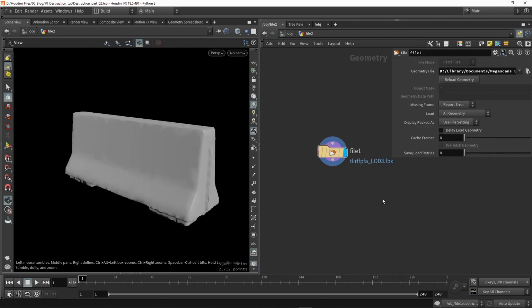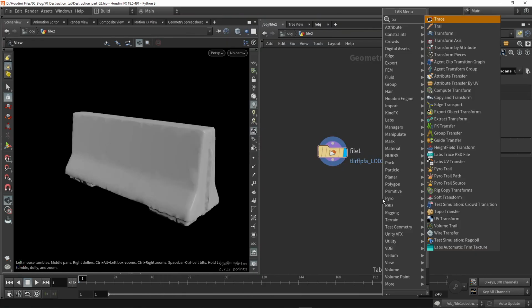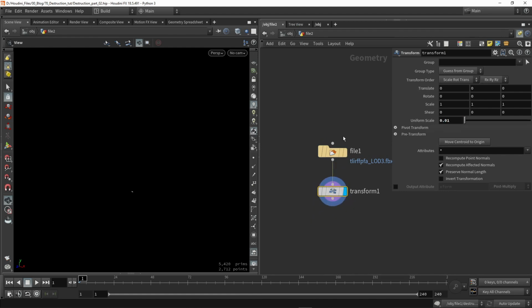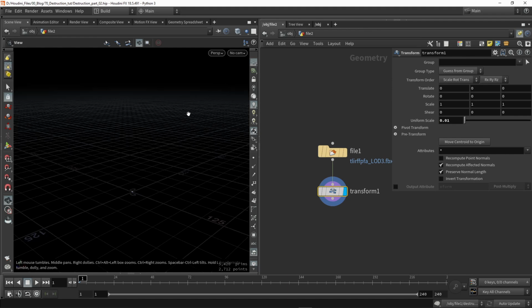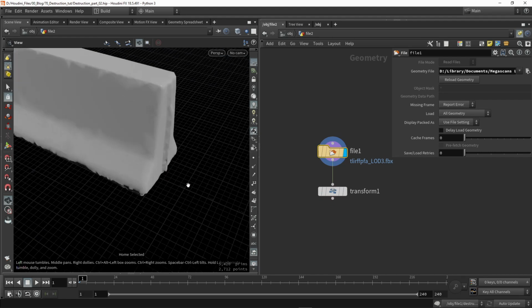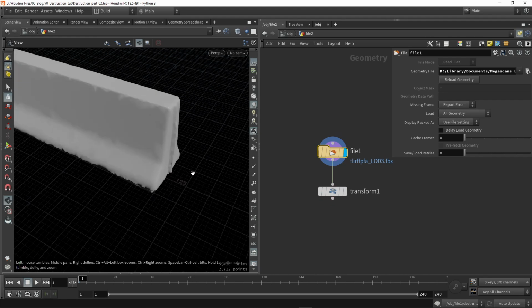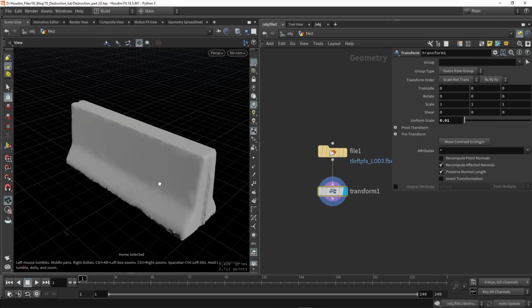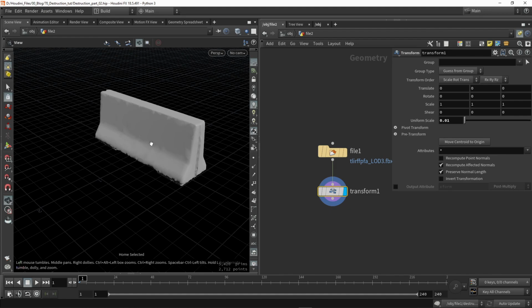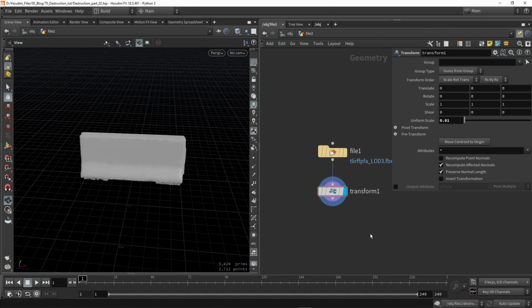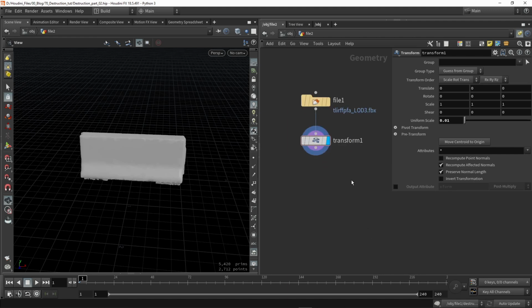Then I also want to scale this down because there is always a 100 unit difference in scaling. So I'm going to scale this down by 100. Now my model is in a better scale. You can see that here I have quite a large scale, and you can see the values on the grid are quite large. If I scale this down by 100, those are better units to work with. I always like to do that to make sure we are working consistently with units